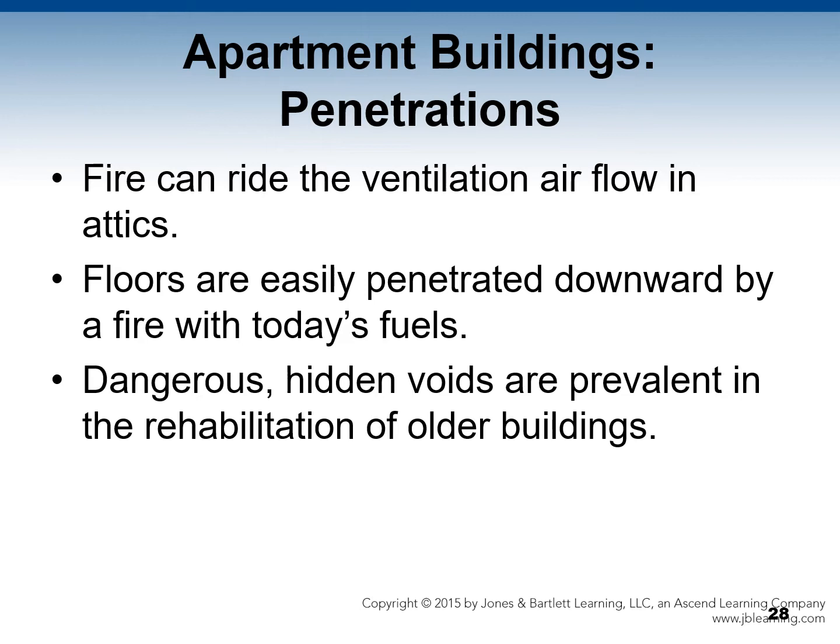Why? Because the hot gases tend to flow up and concentrate the heat upwards, and as I said before, everything's going to burn given the right temperature and circumstances. So there is no such thing as a rated top floor or attic ceiling. Dangerous hidden voids are prevalent in the rehabilitation of older buildings.